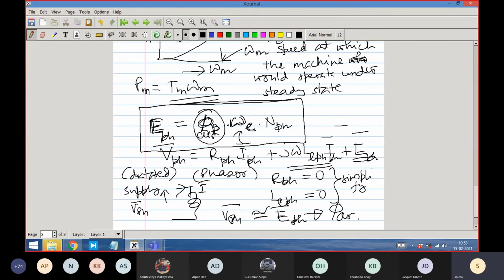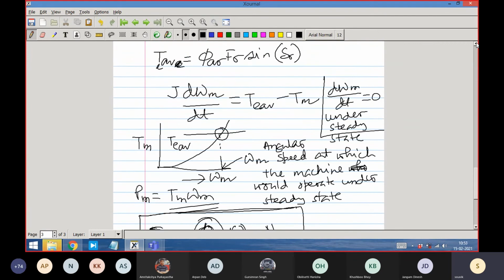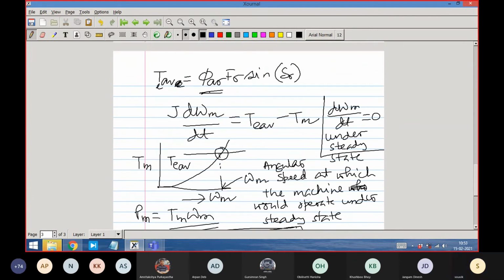That is meticulousness. But the philosophy, which you should never forget, is that the moment you apply voltage, you essentially dictate the flux of the machine, and flux of the machine is nearly equal in stator, rotor, and air gap. MMF is not equal. MMF is created by the stator, MMF is created by the rotor. Combined MMF is creating the combined flux. That is the point, right? So flux of the machine is dictated this way. So in the torque expression, the part that is getting dictated due to voltage is this. This is voltage related. Then we have the play with this.